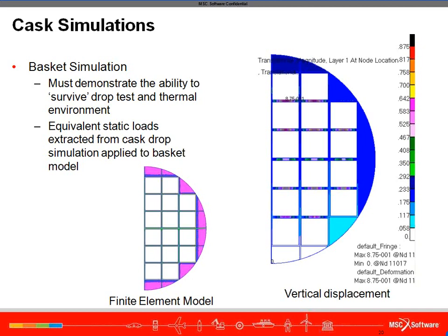Baskets like these are typically constructed of plate steel in a somewhat loose fashion so that the high temperatures that the fuel rods can generate don't induce high thermal stresses. From a simulation and analysis point of view, this means that there can be significant amounts of sliding in contact. And again, our MSC offerings handle this quite well.